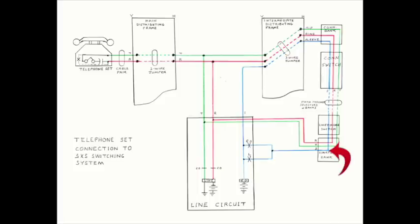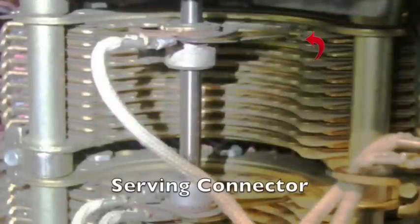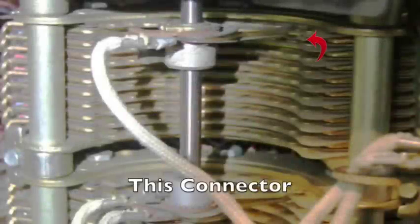If the called station is already in use on an originating call, there will be ground on the sleeve lead of its line circuit, originating from the switch train of that call. That sleeve lead is connected to the connector sleeve bank terminal by way of the jumper on the IDF. This ground will cause the G relay to operate. If the called station is already in use on an incoming call, one of the other connectors in this same connector group will be serving that call, and that connector would be supplying ground to the sleeve terminal of the called station. Because of the bank multiple, that ground will appear on the bank sleeve terminal of this connector, which will feed through to the G relay winding and cause the G relay to operate.